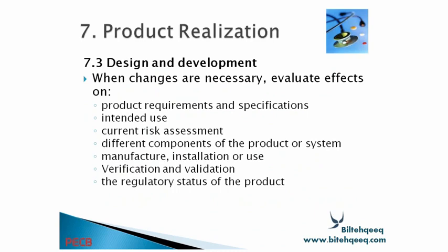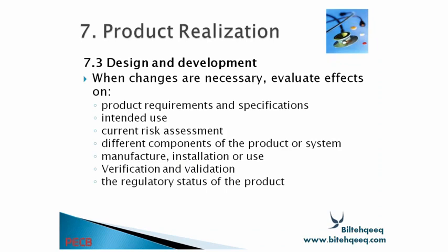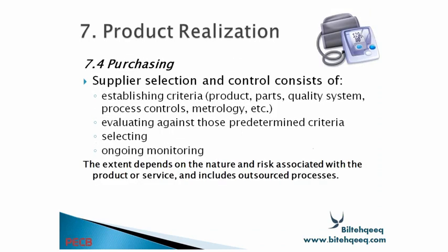You have to also study the effect of the change. If you change the design, you have to evaluate what effect it will have on product requirements and specification, intended use, current risk assessment, different components of the product or system, manufacture, installation or use, verification and validation, the regulatory status of the product. So if you are going to change the design, you have to see each and everything very thoroughly, that what impact it has on the other activities.